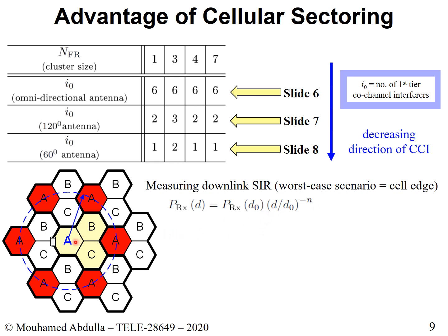We said that is the worst case scenario. Therefore, you will be L meters away from the cell tower. So you could just write that here. And then d naught is the close-in distance. You just have it in the bottom, and you have it to the power of minus n. Remember, in free space path loss, the exponent that we worked with was 2, right? So minus 2 if you bring it up. In general, free space path loss makes sense when you are in line of sight, or when we talk of satellite communication. The path loss exponent for free space path loss is 2. When we talk of cellular communication, the path loss exponent could vary. In fact, the feasible values for the path loss exponent could be anywhere between 2.7 to 5.